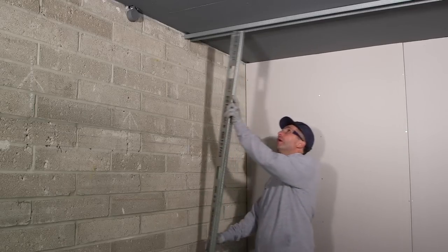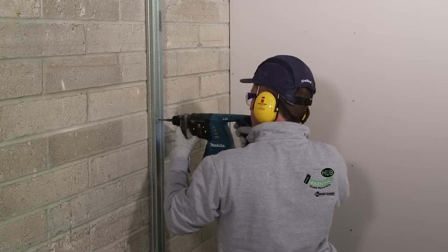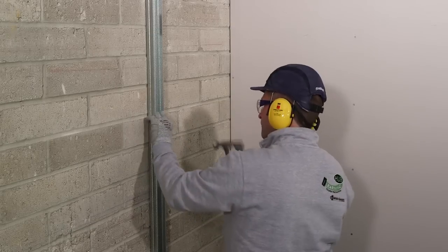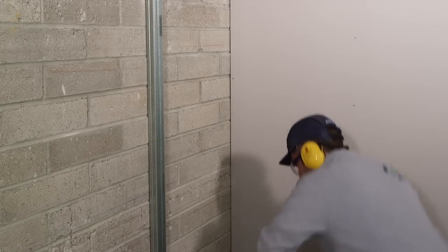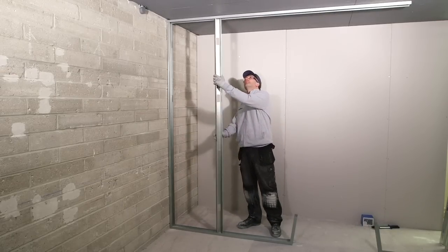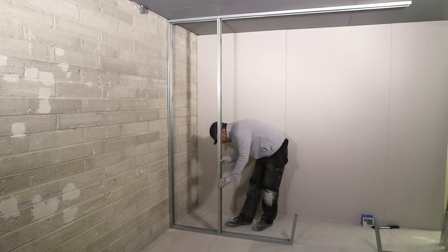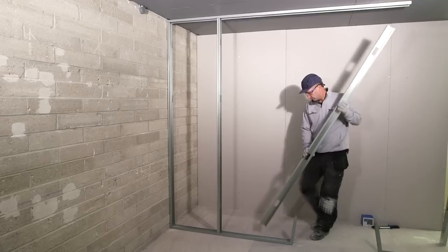Locate the stud against the masonry wall, installing proprietary fixings at 600mm centres, and for wider Gypframe studs, 2 rows of staggered fixings at 300mm centres. Locate further studs into position at 600mm centres. Note the only fixed studs are at wall abutments, external corners, and opening positions in the partition.